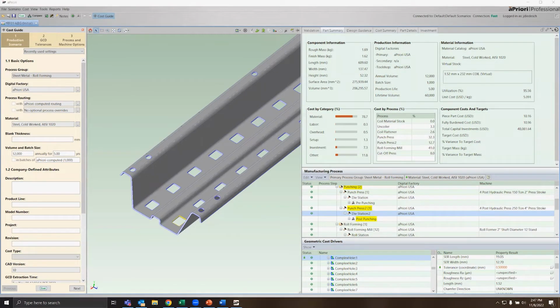You should also note that while pre-punching typically is performed with a stationary die, post-forming punch dies and the cutoff die need to be accelerated, so they are moving at the line speed when they contact the part. We calculate what types of speeds are achievable given the mass of the punching and cutoff dies and the distance they have to accelerate, which is the length of the part. The achievable die speed may limit the overall line speed.